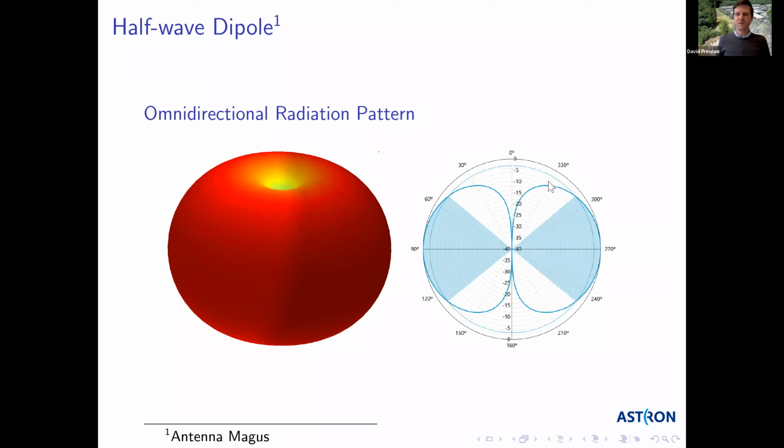Now, in terms of directivity, the directivity of a dipole is around 2.15 dB. This is just an arbitrary value for you, but it's not a lot, in other words, because as you can see, it's not quite isotropic, but it's only a small part where it doesn't radiate. So most of its power is still radiated across an entire sphere.